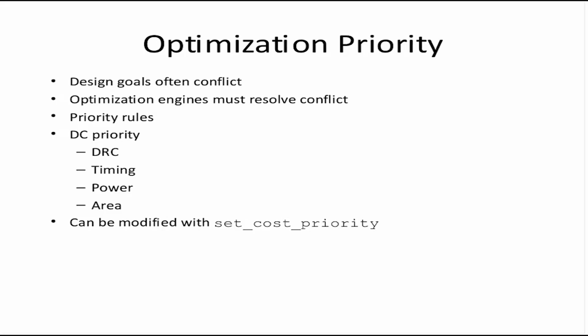So that was all about design partitioning. Till now, this concept was only theoretical, but when you start coding, you would start appreciating the value of each of those principles later in the flow. So if you do not register your output, you will find at a later stage that you are having problems in defining timing constraints, and then you will go back and probably register the output. So it's good to know these concepts beforehand so that you can actually use them in practice.